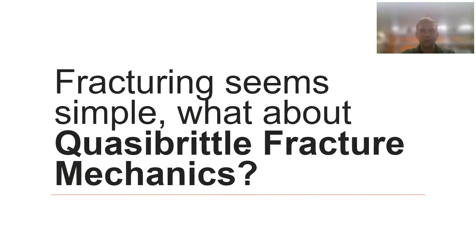So we just learned a little bit about LEFM and how this is applying. What about quasi-brittle materials? Because we just talked a little bit about how that fracture process zone was different and how the stress wouldn't build up at the tip, but then we went back on our word and said that it would. Well, that's because we were defining LEFM. Now we're going to transition into our quasi-brittle fracture mechanics.